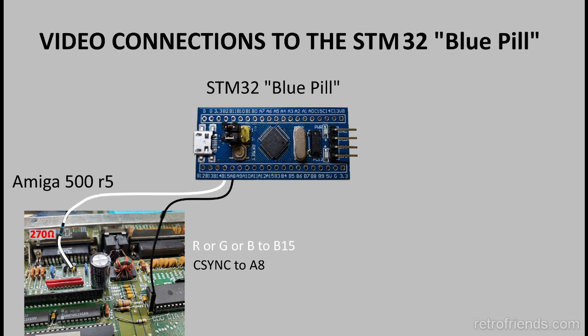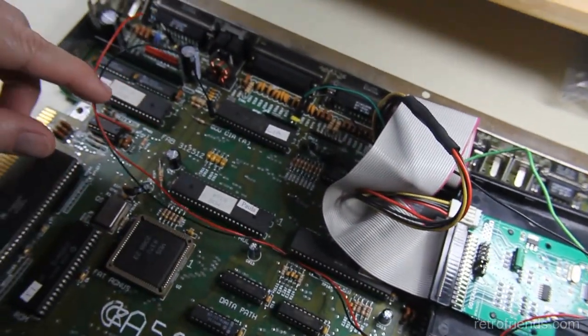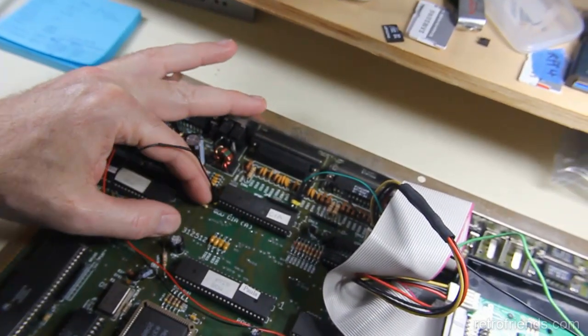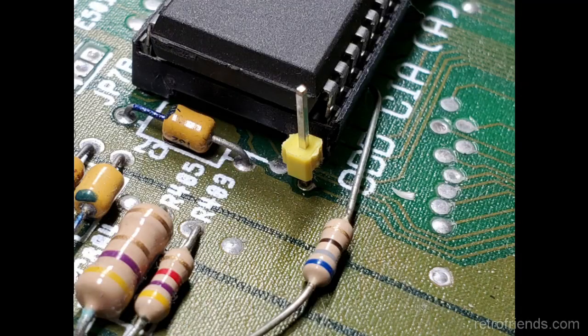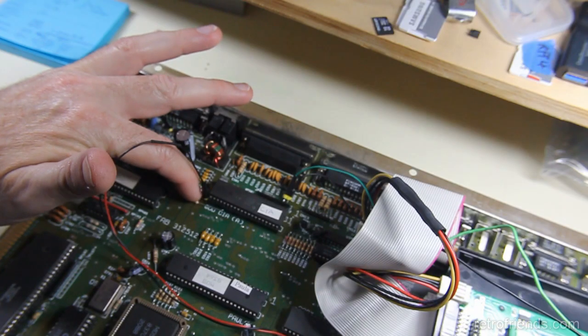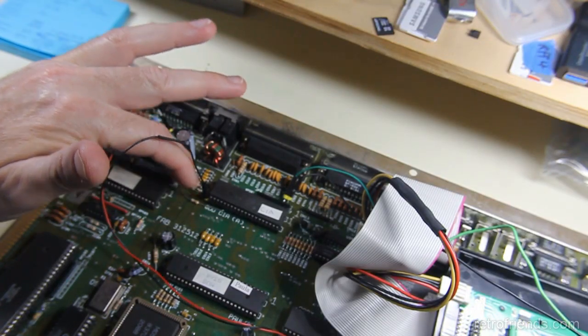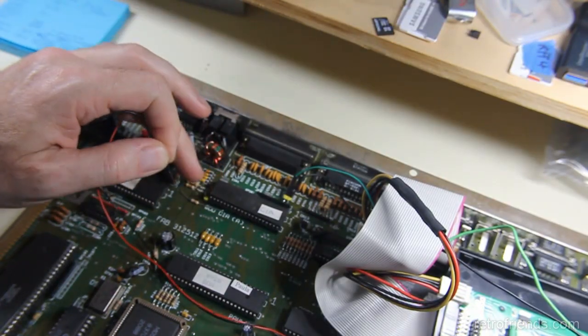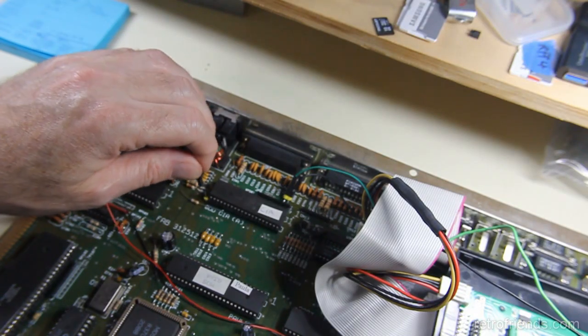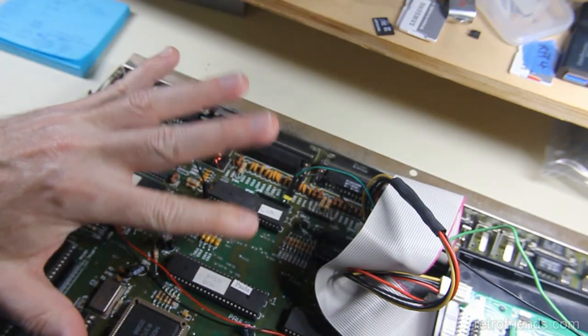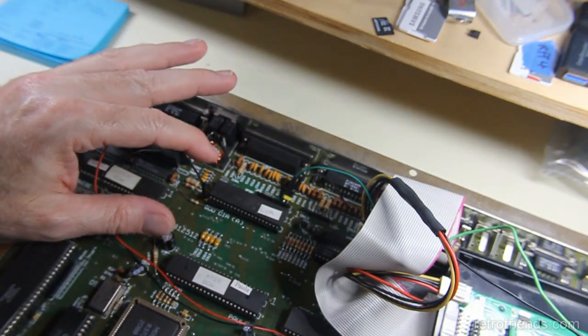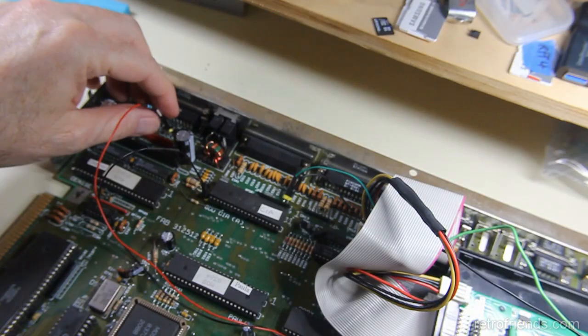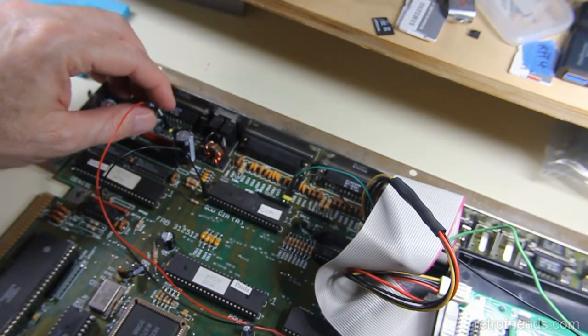It's A8 on this board, so it's black, and it comes over here and connects right next to the CIA chip right here. And you can ring that out with Denise. It's one of the outputs of Denise, but they're pretty good on the wiki showing you where to solder that to. There's a nice pad, an open via that's not being used, that you can solder it into. And I actually attached jumper pins on all these so that I could remove everything, because this is Steve. I call him Steve. I repaired him and I use him as a test board, so I figured I could just leave these jumper pins in here for future.